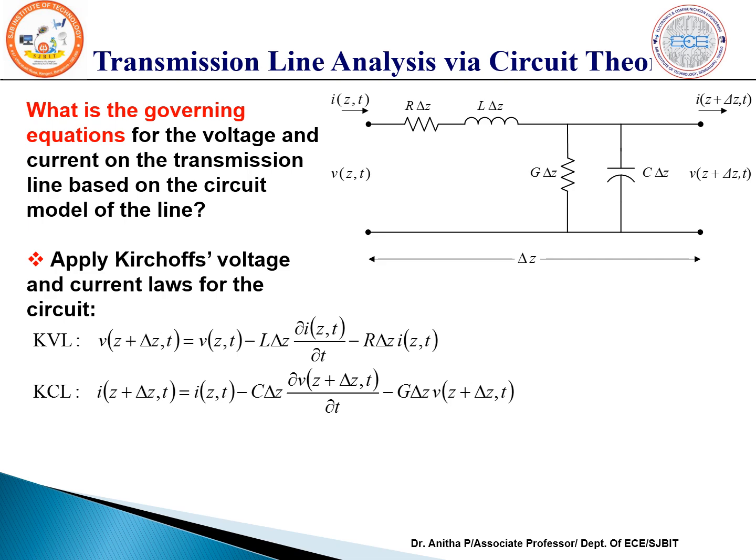Current leaving through conductor and capacitor. So current, if I want to determine, I is equal to C dV by dt. So C value is C into delta Z, dou V by dou T. Voltage drop across that. So similarly, current through this conductor is G into V. So G value is G into Z multiplied with the voltage drop across that. So we have applied KVL and KCL, written a governing equation, rearranged that equation.